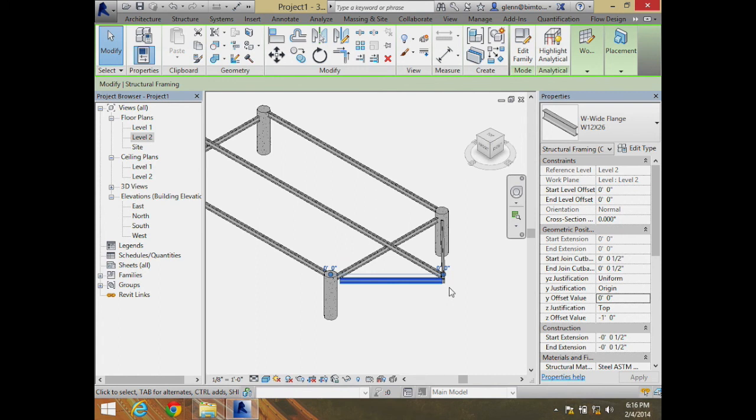But you can go through and approximate the curve that way. And if that curve is still a little bit too approximate, you need it a little bit smoother, what you can start doing is actually putting other ones that are kind of coming across in between. You're going to break that instead of 2 segments into 4 segments, or as many segments as you basically need it to be. So, yeah. And the big thing is really just to basically introduce structural support where it isn't by putting a cantilevering beam out there to go ahead and pick it up.